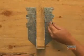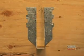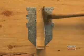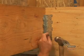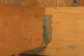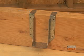When installing many types of hangers, fasteners are driven through holes in the header flanges, into the carrying member, and through holes in the side plates and into the carried joist. Some hangers also have top flanges. Top flanges hold the hanger in place during installation, which makes installation faster and easier.